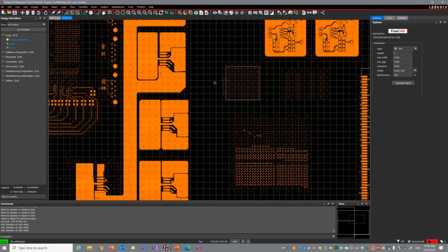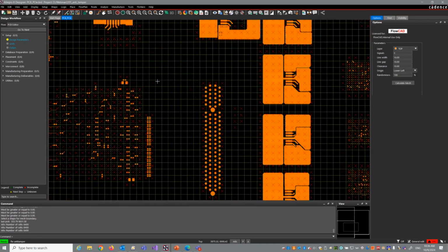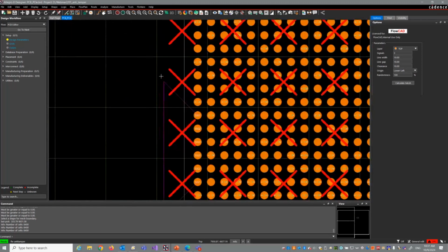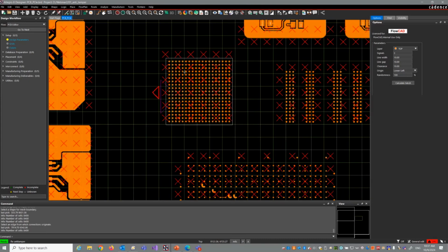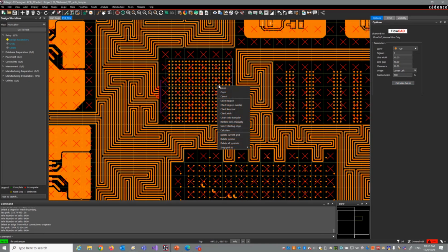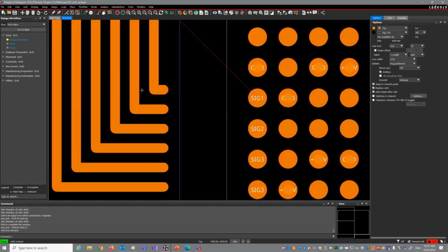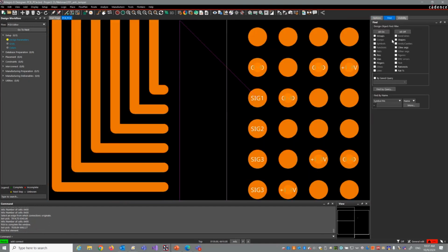So now we are done, and you can see here all the remaining cells which are still open will now be processed by the application. Where do we start? Right mouse button, select starting edge. We want to start here. And now we press calculate. So we may now start routing from here.